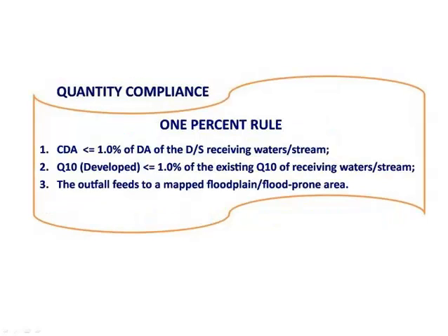Stormwater conveyance systems shall be analyzed for compliance with channel protection criteria to a point where either, based on land area, the site's contributing drainage area is less than or equal to 1% of the total watershed area, or, based on peak flow rate, the site's peak flow rate from the 1-year 24-hour storm is less than or equal to 1% of the existing peak flow rate from the 1-year 24-hour storm prior to the implementation of any stormwater quantity control measures.